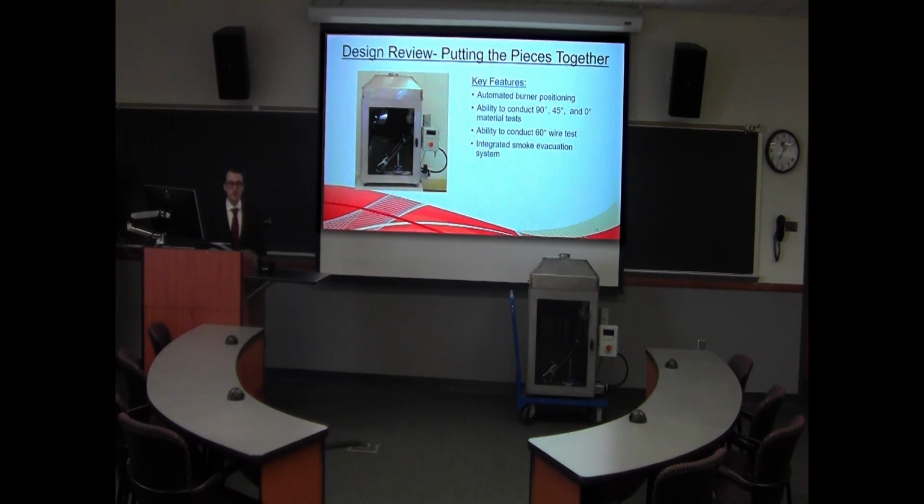As we've shown throughout the presentation, our testing cabinet accomplishes the primary requirements for FAA approvability. A key feature that the current cabinet has incorporated is an automated burner movement system for accurate and quick positioning of the burner for each individual test. The design also has the capability to perform 45-degree, 60-degree wire, vertical and horizontal tests within a single cabinet enclosure.